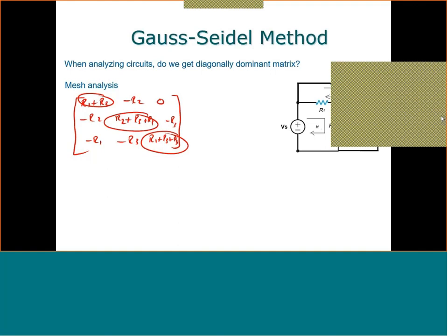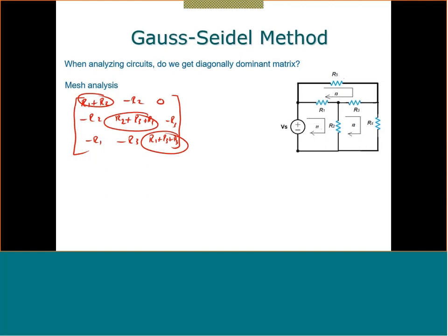For the nodal analysis question, you are solving, what about KCL at VS? Oh, we don't. This is a circuit question. We don't apply KCL at a node where we know the voltage. VS is a voltage that is given to us. We know it, so we don't. The only two unknowns we have are V1 and V2. So we don't apply KCL if we know the voltage.